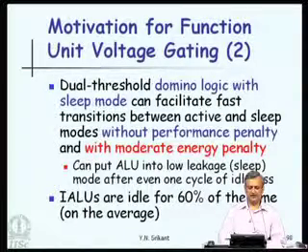So, there is something called dual threshold domino logic with sleep mode. This is an electronic circuit, and this can facilitate very fast transitions between active and sleep modes. In other words, when a function unit is in active state, the full voltage is applied to it, and when it is in sleep state, the voltage is made 0. So, this is the transition that we are talking about between active and sleep state.